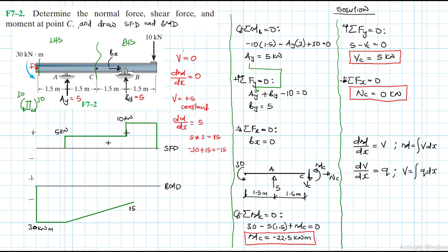And then for this other region here, we need again to compute the area. The slope will still be positive. So the area there is equal to 10 times the length, which is 1.5. So this gives us a 15. But where we are coming from, we have this initial value, which is minus 15, plus the new value that we just calculated, which gives us a 0.